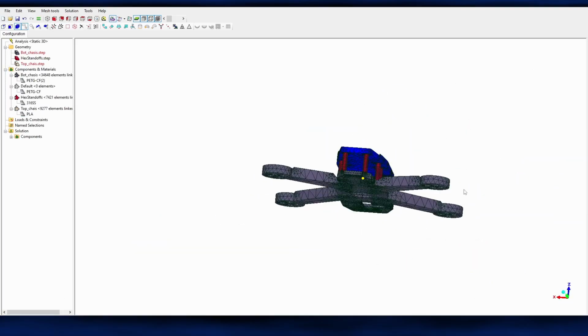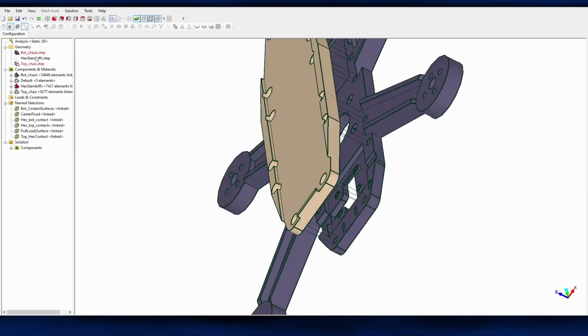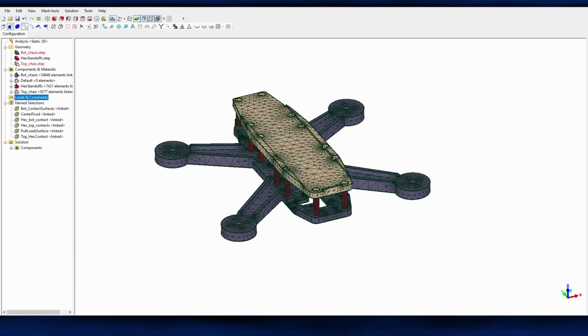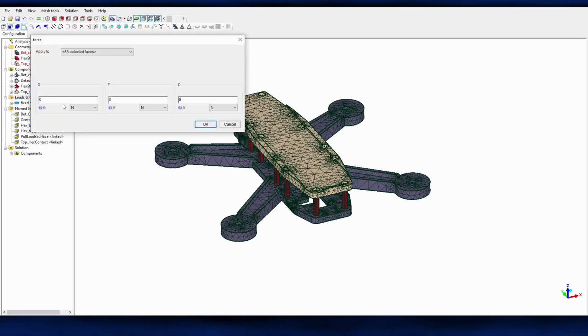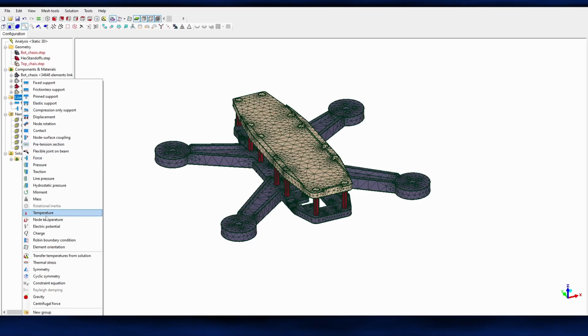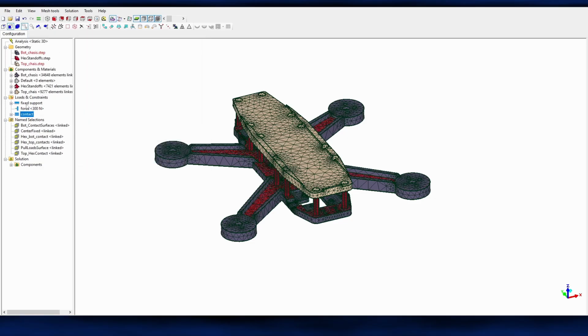Also bear in mind that we are validating the design of the PETG carbon fiber part. An impact does not spread evenly across the 4 edges and is hard to predict. However, since I've already accounted for enough safety factors, I will divide the force equally among the 4 motor arms. We only keep that in mind, and we can always evaluate our results and modify the analysis for scenarios closer to reality. Now, let's set the boundary conditions.